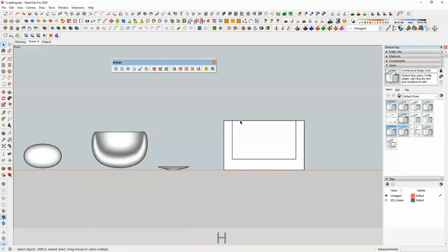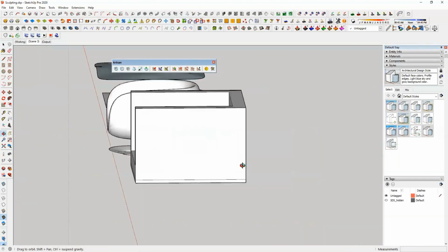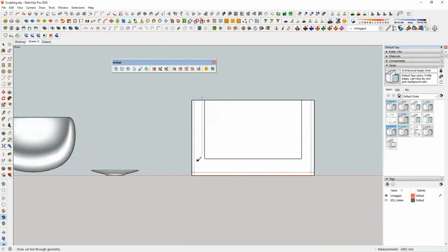To create divisions, I'm going to go with orthographic projections, and here we have a knife option. As you can see, the knife subdivide, and what we can do with the knife tool is create more subdivisions, and this subdivision will be through and through. That means if I click cut here, this cut will continue in the other direction as well. That's why I'm using it in the orthographic projection. So let's pull this downwards, and if we have more subdivisions, then we will get a different result.